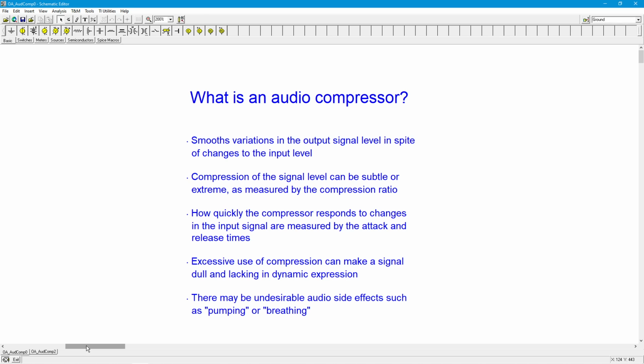We'll drive a little lamp or an LED, something like that, so that as the signal goes up, the light source gets brighter. We encapsulate that with the LDR, right? So no outside light gets in. So as it gets brighter, that resistance goes down. We use the LDR as part of a feedback loop in an amplifier. So as the signal gets larger, the light gets brighter, the resistance goes down, and the gain goes down, right? That's a very basic idea of doing that. You can make very simple compressors using that idea.